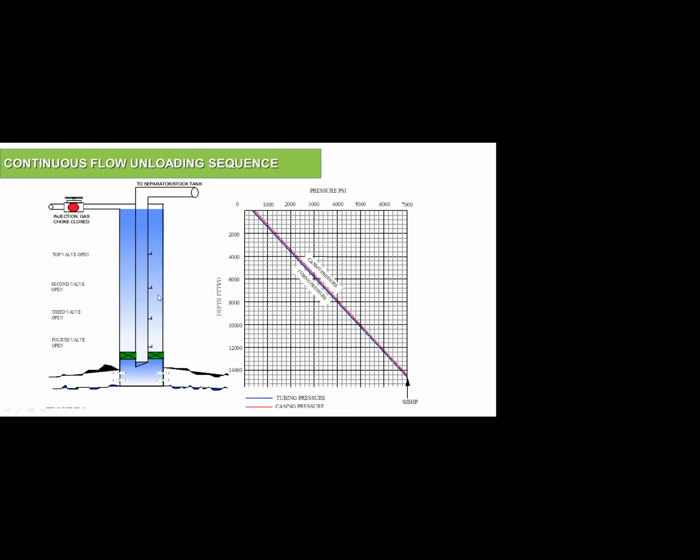Normally, you drill the well, complete the well, and then you install your tubing and set the packer and stuff like this. And the well is loaded with the completion fluid. You have to control your pressure. Then you want to produce the well. There are one of two scenarios. Either I have only one valve here, but if I try to inject gas, it will not go down because we need very high pressure to go down. From the beginning, we have a compressor system and only limited high-pressure injection gas, for example 1,500, 1,000 or whatever. So I cannot produce until I remove this fluid inside the wellbore.